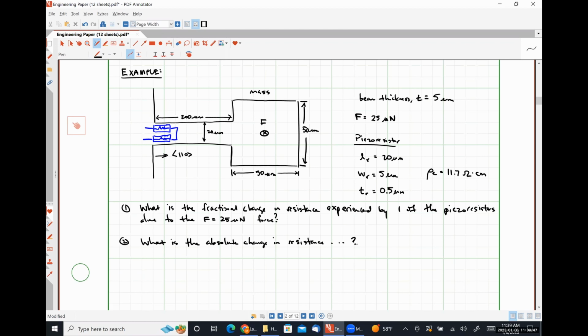that we can say with a reasonable degree of accuracy that effectively the piezoresistor experiences the same stress throughout its length. That won't actually be true, not even close to it, but it's going to give us a reasonable approximation. Whereas if we made these piezoresistors the entire length of the beam, we know for sure that's not true, and we're having a very, very poor approximation, okay?